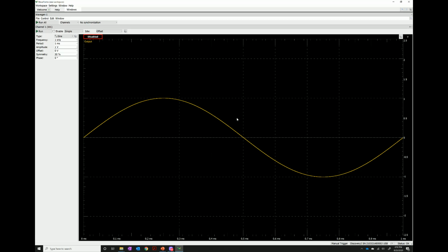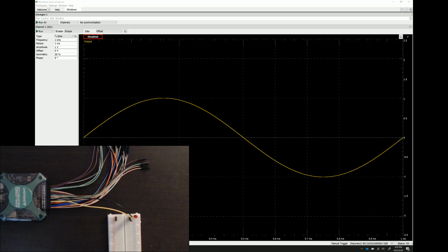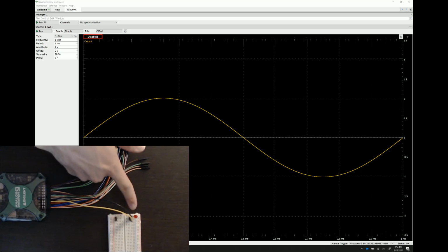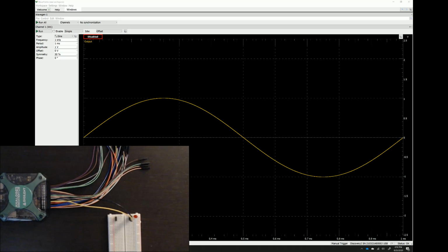On our AD2 board, we have a simple setup with pin W1 connected to the anode of our LED and our ground pin connected to the cathode of our LED. Note that a diode ideally has a fixed voltage drop, so we would usually put the LED in series with a resistor, but the AD2 board does have some internal resistance, so we can actually attach the signal directly across the LED as we've done here.